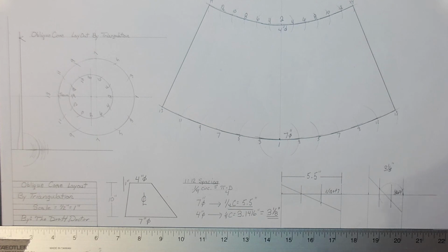A lot of times we find cones that are long and drawn out in dust collection systems or particle removal systems. In these cases, velocities are very important, and the fittings, the transitions are long and drawn out, and the reason for that is to keep them from plugging up. We make it using triangulation because we have an apex that is way far away from us. We can't deal with it. It's too far. Triangulation is the be-all, end-all. It takes a little bit of time. It's extremely accurate as long as we are accurate working with it.